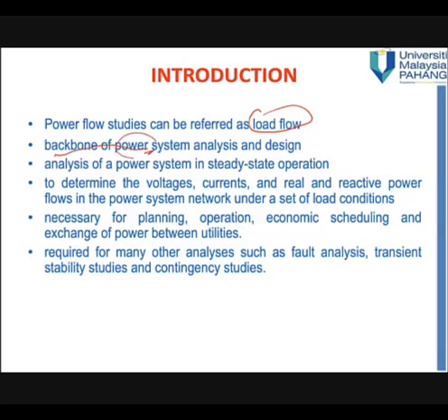And normally it is referred to the steady state condition, meaning there is no fault happening. Basically, what is the load flow? We want to know the value of the voltage, the currents, as well as the real and reactive power flows in this power network under steady state, under a set of load conditions.